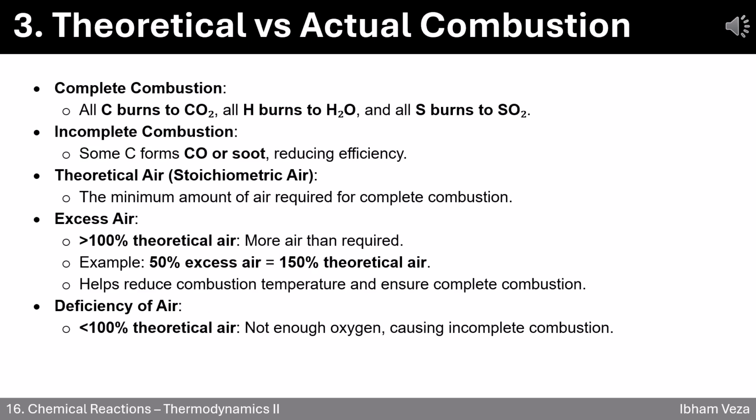3. Theoretical versus actual combustion. Now let's talk about the difference between theoretical and actual combustion. In an ideal world with complete combustion, all carbon turns into CO2, hydrogen into H2O, and sulfur into SO2. This is the cleanest and most efficient outcome. But in reality, incomplete combustion happens, especially if we don't supply enough air. This leads to carbon monoxide, CO, or even soot, which wastes energy and creates pollution.